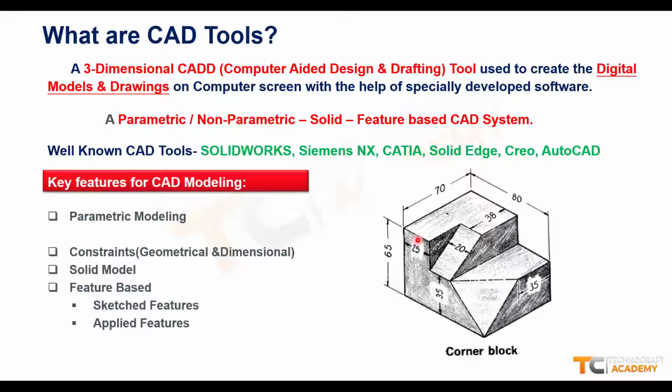Good. If you assign the material for this, then only will this particular model be called a practical real model, because until you assign the mechanical or geometrical properties, let's say to check the weight of the component, what do we need as a main mechanical property? Material, which material we are using. In the material we need to know the density.